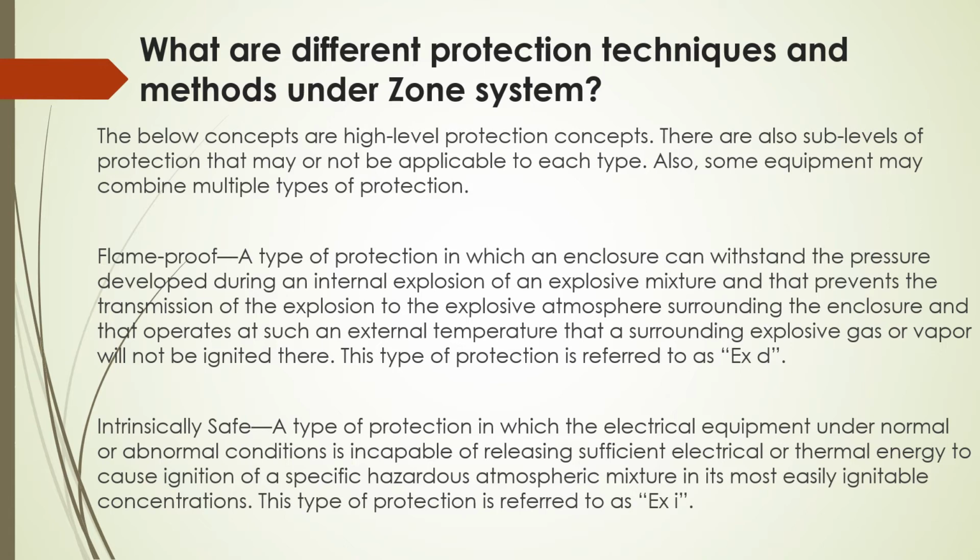Flame proof, a type of protection in which an enclosure can withstand the pressure developed during an internal explosion of an explosive mixture and that prevents the transmission of explosion to the explosive atmosphere surrounding the enclosure, and that operates at such an external temperature that a surrounding explosive gas or vapor will not be ignited thereby. This type of protection is referred as EXD.